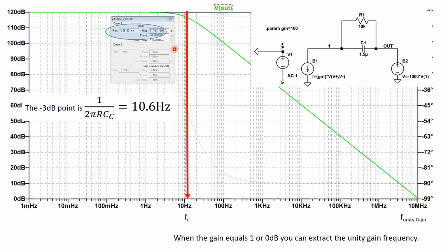you know how we talk about the open loop gain going towards infinity? Well, really, if you have a circuit with a gain of 1, an open loop gain of 100 is effectively infinity, right? If I have a gain of 10, well, it changes a little bit, but an open loop gain of 1,000 is effectively infinity, all right?